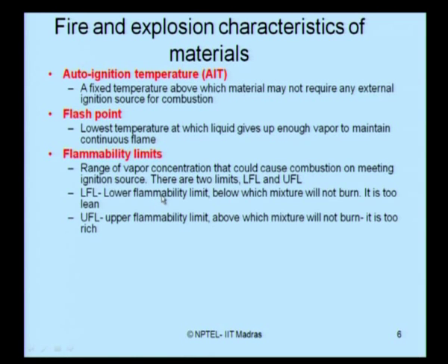So it is between these two limits that the vapor concentration could cause combustion in the presence of an ignition source. So, ladies and gentlemen, by any chance, if the concentration in a process plant like the petroleum industry is between the LFL and UFL of the material, and if you unfortunately have an ignition source present on board, then there is a probability that the material or the mixture can catch fire.